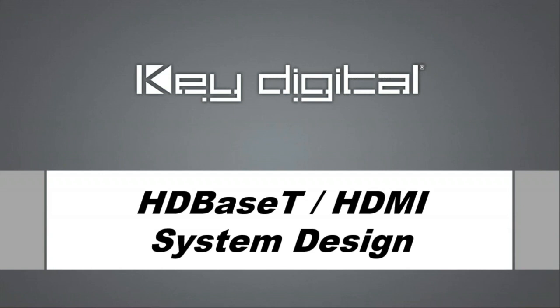HDCP failure, like a static screen, if that display data channel has been corrupted due to noise in the environment. The point is, HDMI never tells you straight up what the problem is. You have to be able to observe the problem and deduce which of those layers you need to